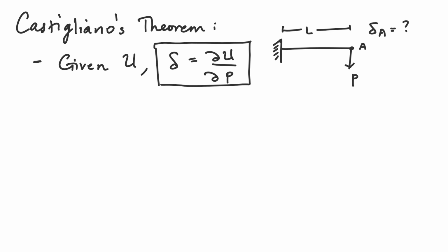First, we have to calculate the strain energy. And this is another thing that you should memorize. The strain energy for a beam is equal to the integral from 0 to L of M squared over 2EI dx. However, this is only considering bending moment.